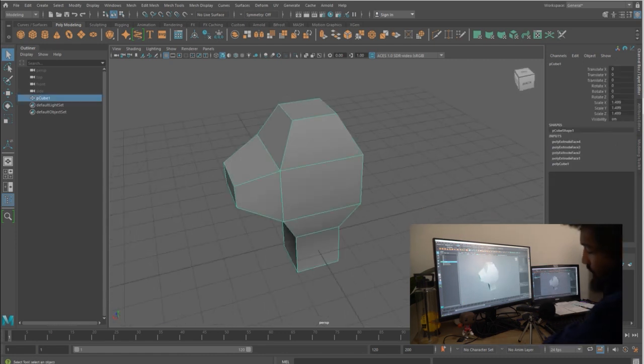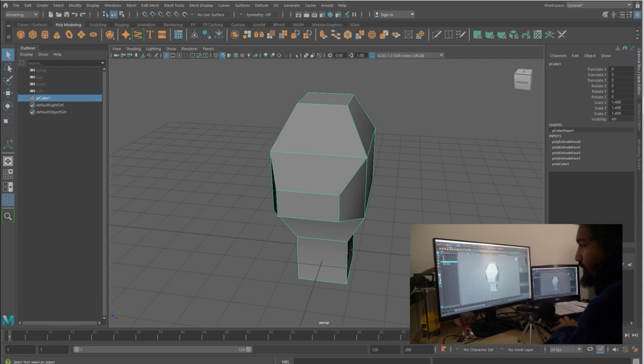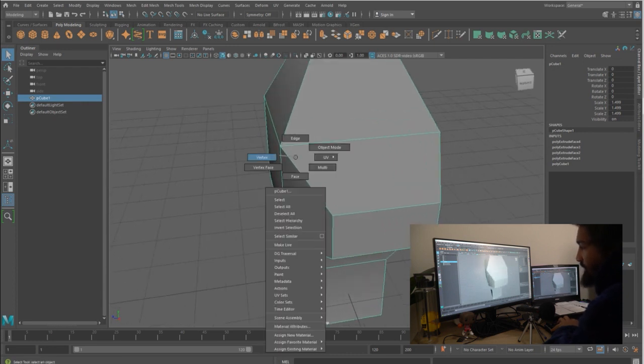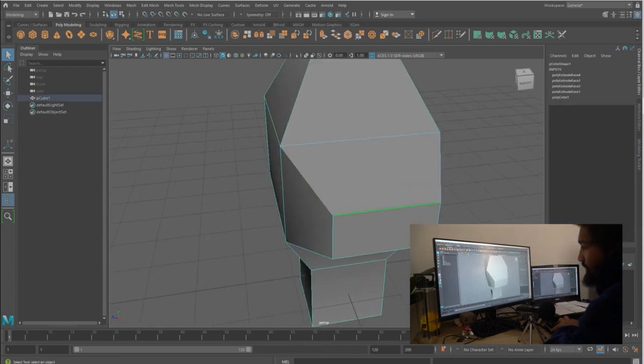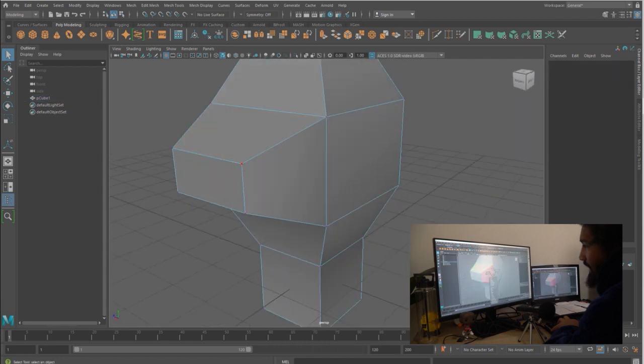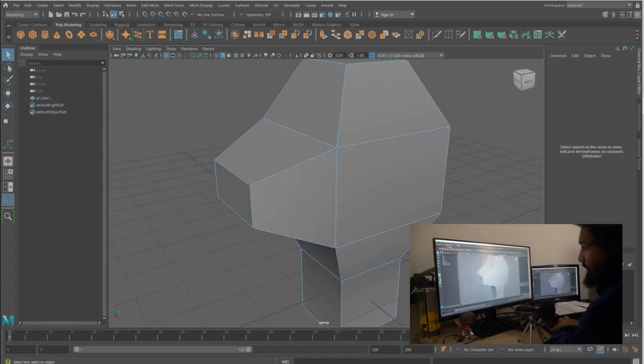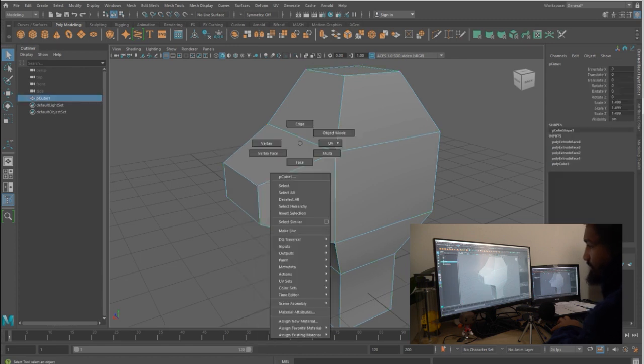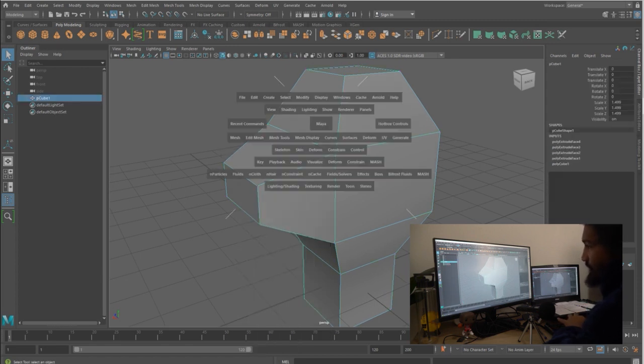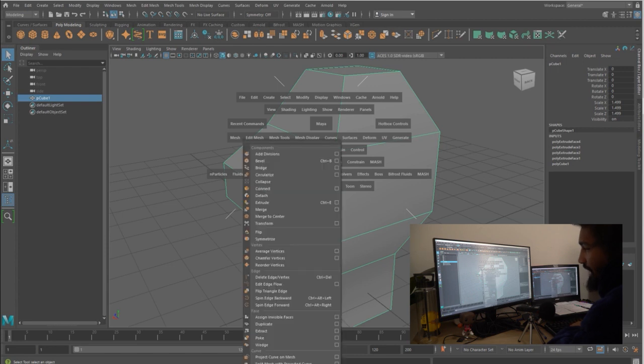In modeling, we want to make sure we work with 4-sided faces for simple assets. When we have triangles, it's for very specific reasons, like characters or other mesh solutions. But we really want to work with faces of 4 edges. So 1, 2, 3, 4, 1 face, and 4 vertices here. So that's the way. You can also do what we call edge loops.